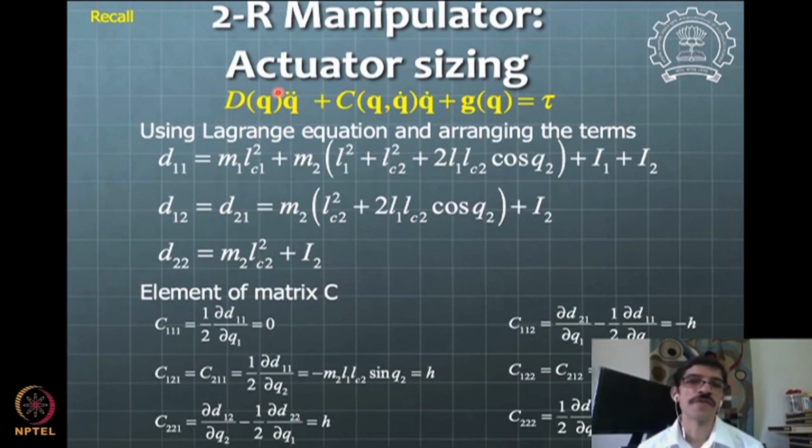So once you have estimated a torque here, you can consider that this comes as tau 1 and tau 2, the torques in the first motor and the second motor. Then, by substituting your desired trajectories, you use torque times velocity as a power estimation for the motor, and this torque will give you the maximum torque along the trajectory.